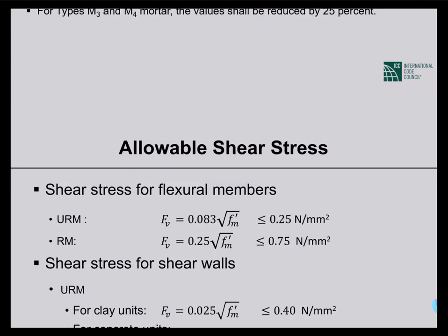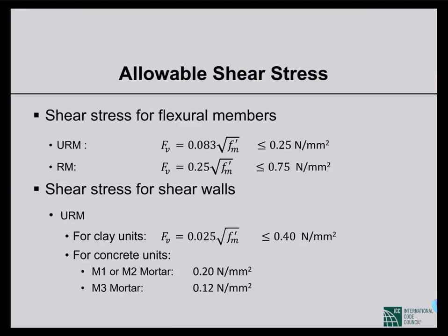Now, allowable shear stress. So we talked about compressive stress and then tensile stress, and now let's talk about shear stress. This is probably the most important type of stress, because in most of the cases the lateral loads are carried by shear walls, masonry shear walls in masonry construction.